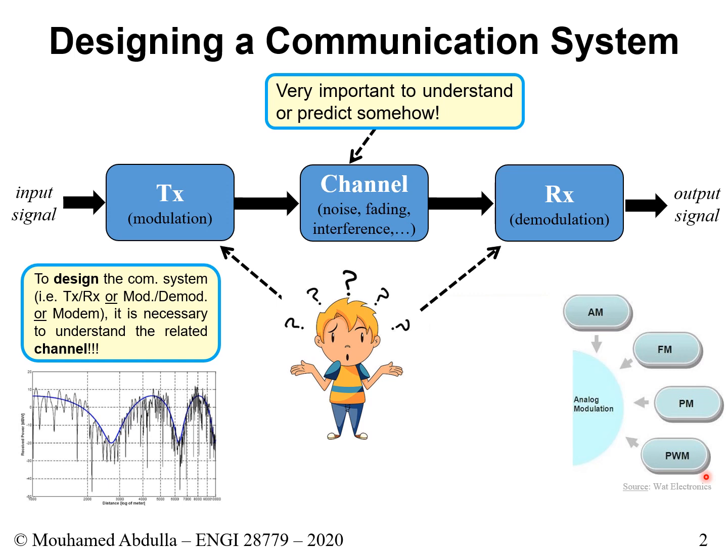So essentially what it does is that the information is encoded in the width of a binary pulse. So you have a pulse that's 0 and 1, or if you want 0 volts and 5 volts, or 0 volts and 3.3 volts, and within the pulse of a 3.3 volt, that's where the information is, right? That's the value of the amplitude of your analog signal that is encoded.